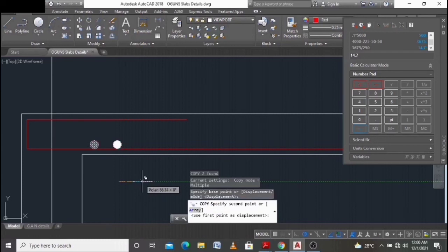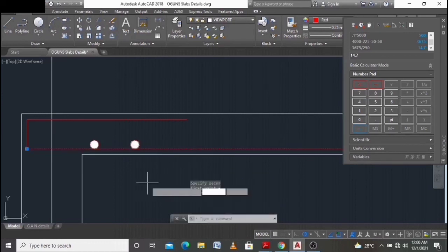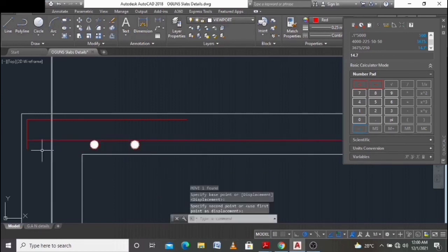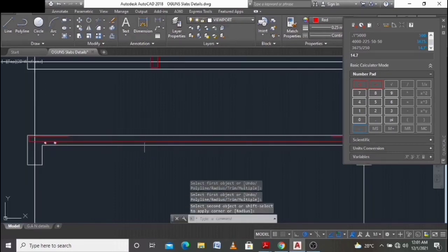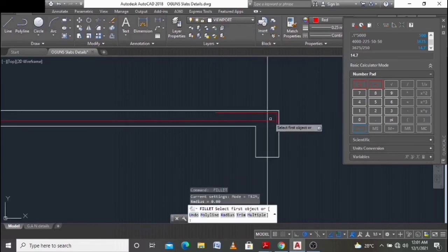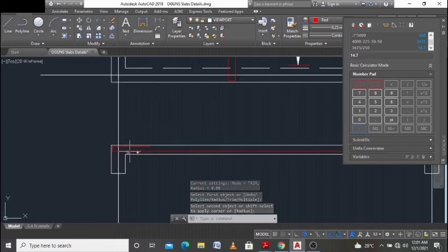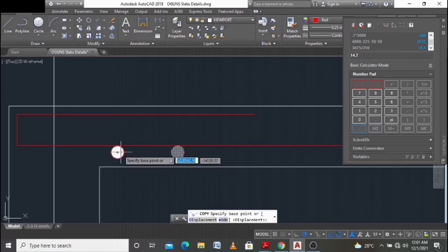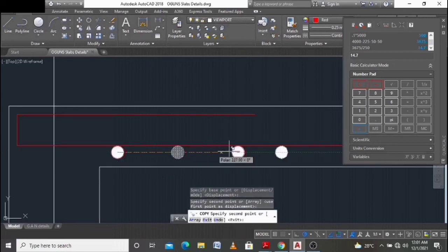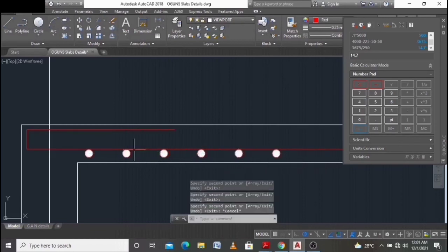So it's not going to be like this, it's just going to be a little bit different, such that this is going to be above this reinforcement, because as I explained, this is the bottom reinforcement, this one is the bottom distribution, while this is the bottom reinforcement, and whatever you do on that plan must be well represented on the section. Yes, so you see what it is.